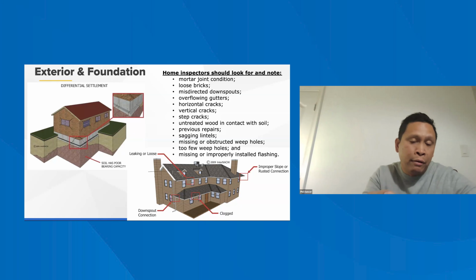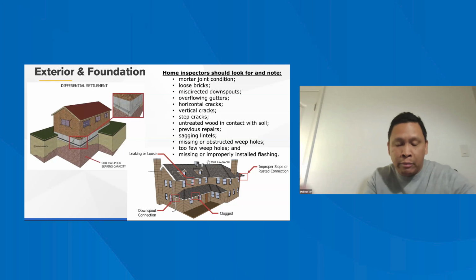But just know I can't see through this wall, and it may or may not be transitioning through. But then also, if that crack was coming from the large opening, so window or door or beam pocket, then I would suggest adding another sentence that says this crack is located in a weak point in the foundation where there is a higher probability for this to transition through. And the only way to know is to remove that wall on the other side, the drywall or the insulation itself.